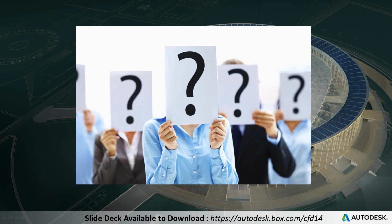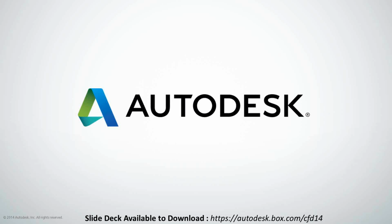We have another question here. Is Nastran In-CAD and Nastran the same thing? No, they're separate products. Nastran In-CAD is an add-in for Inventor that uses the Nastran solvers to perform FEA analysis, whereas Autodesk Nastran by itself is just the solvers, and that's provided with Simulation Mechanical 2015 R1 and now 2016. You get access to the full Nastran solver capabilities with the Nastran editor.